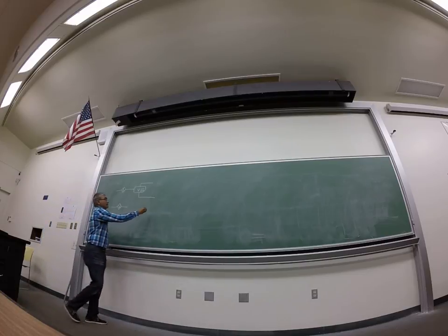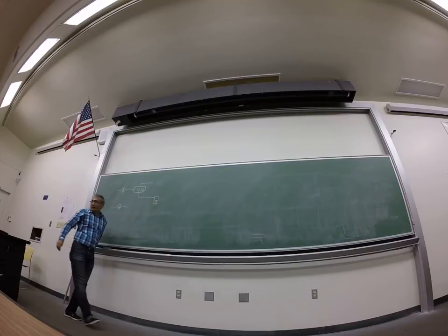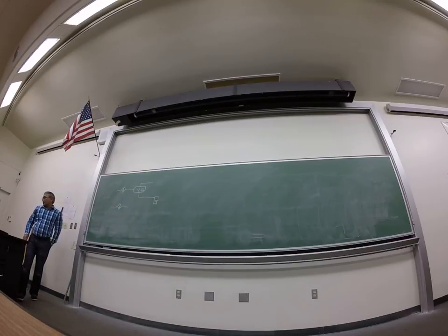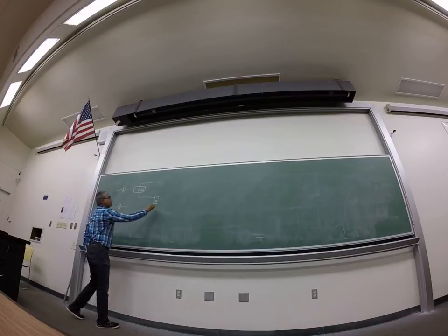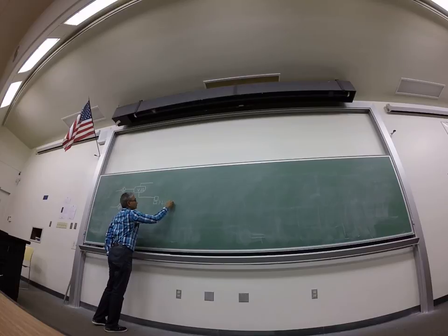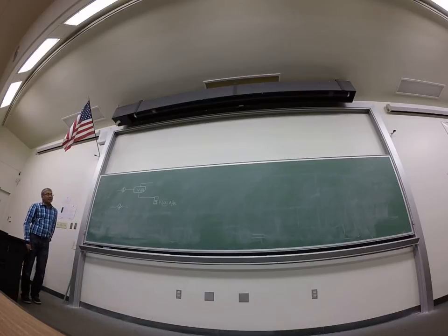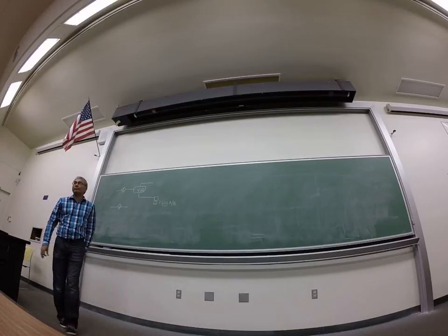So anyway, next is a pump. The pump is drawn like this. Okay. And it's P101 A/B. So P for pump, 101 again is region 10, pump 1. A/B basically means that there's a backup.